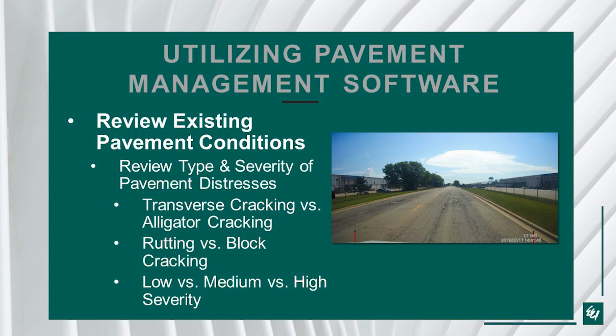What's important is to determine those types of distresses and what they mean. So, transverse cracking versus alligator cracking, that's a difference between whether or not you potentially have an issue with your base, or if it's just an issue in the surface.